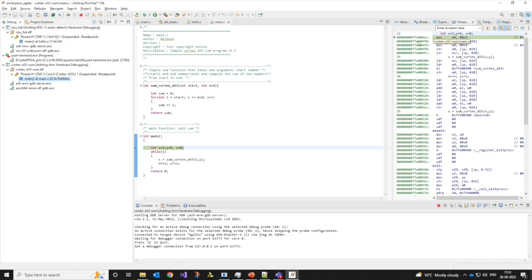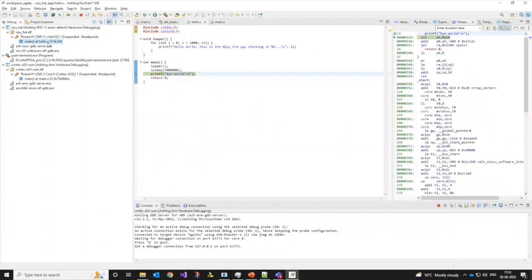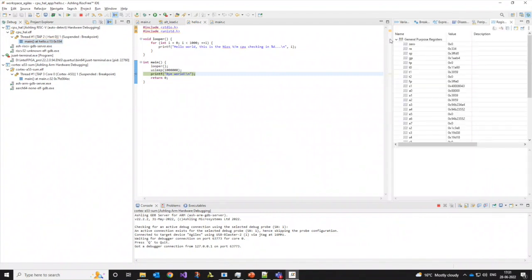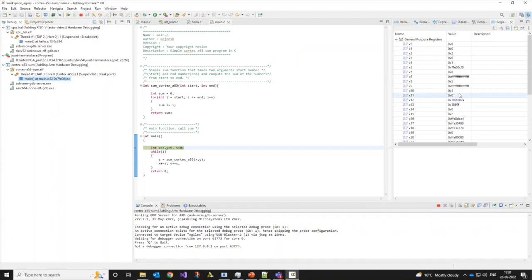And you can see the switching from 32-bit to 64-bit as well. So these are all ARM instructions. And clicking on RiscFree will bring up the RiscFree instructions. So the entire context changes, not just the disassembly view. If I have the register view open, here we are seeing the Nios V registers, but if I click on here, I can see the ARM registers.